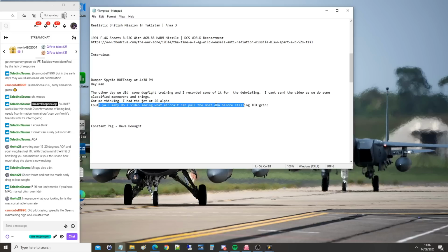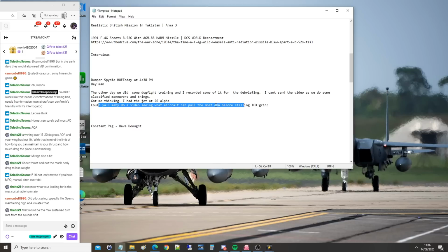Another thing I should say is that this is not about maximum sustained angle of attack in, for instance, an airshow high alpha pass, because you could get really high like that. You could get like 40 degrees maybe in a certain plane. What we're looking at is combat here. Actual usable, turnable angle of attack in a real life knife fight. So now we know what we're looking for in a knife fight: sustainable angle of attack.